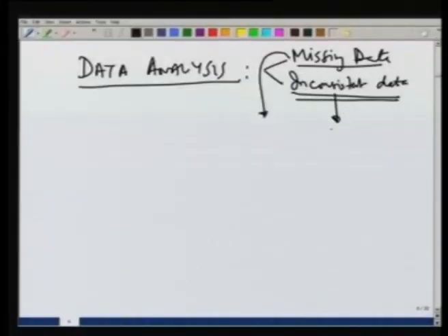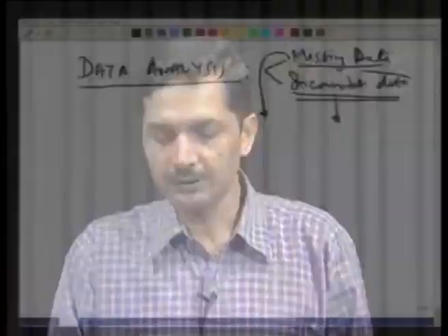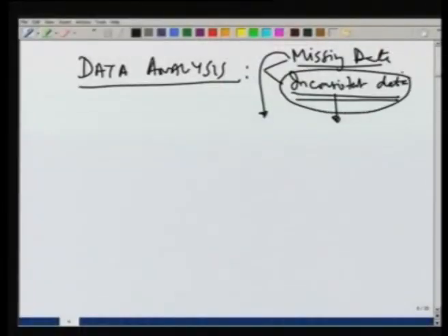again it may be caused by various factors, and some of them may be moving the rain gauge from one location to the other, or change in the environmental conditions near the gauge. And inconsistency, we saw how to remove by plotting the precipitation at that station with, let us say, the average precipitation of 5 or 10 or 20 nearby stations. Typically about 10 stations are used, and what we get is a double mass curve which shows